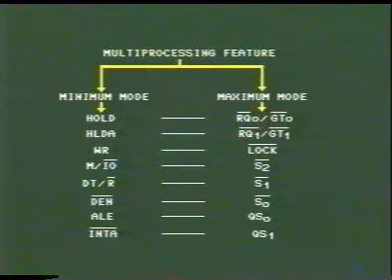With the help of these lines, sharing of any common resource such as memory can be achieved between the 8086 and two other processors. A bus arbiter chip can also be used when the number of additional processors exceeds 2.